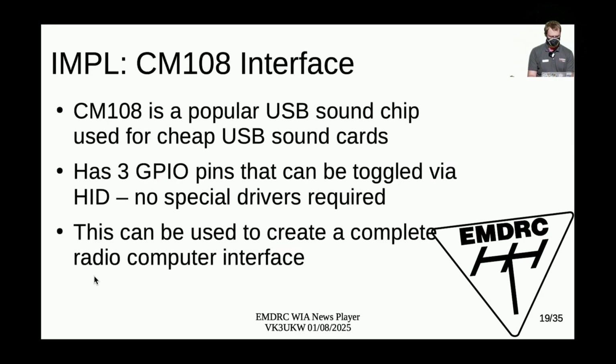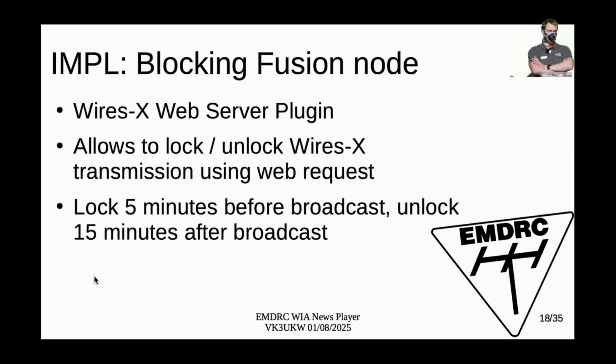No, we got one other thing, blocking the Fusion node. On a computer in the back there we have the WiresX node software, the WiresX software from Yaesu connected to a Yaesu FTM-9000 digital radio. And that has a web server plugin. With that plugin, you can just use a web request to lock and unlock the transmission or the repeater functionality.